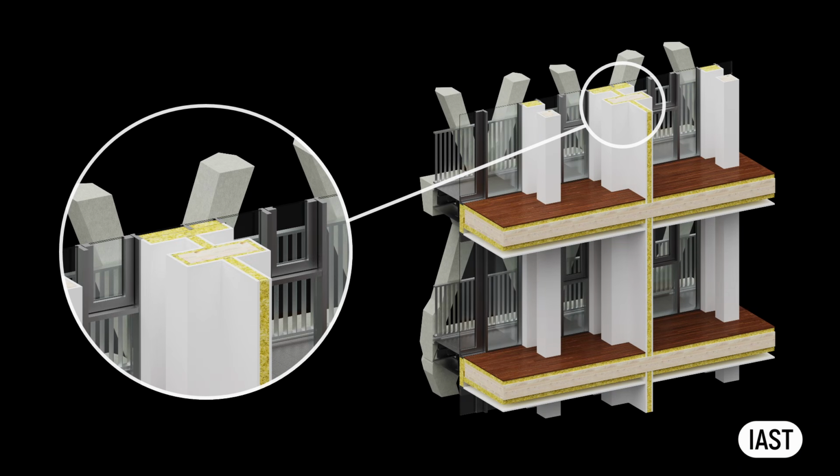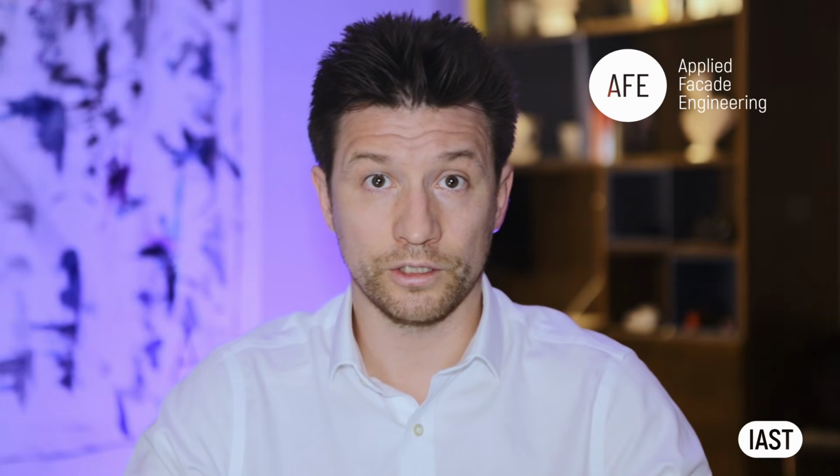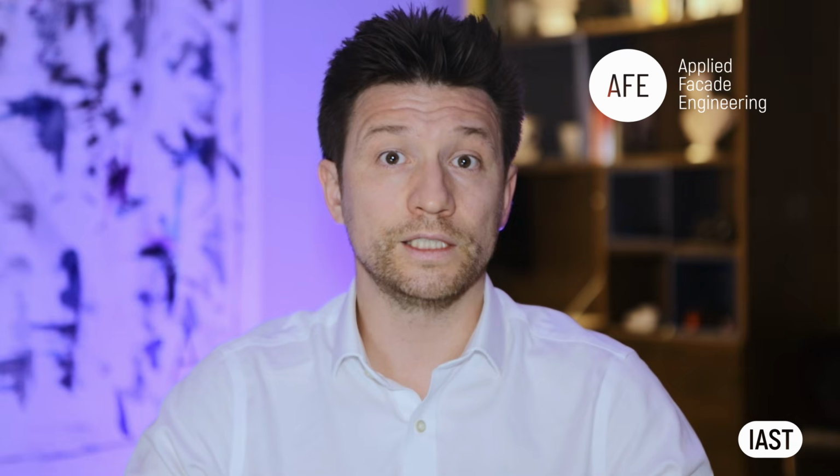When it is used as a primary framework, it should be protected by fire-rated materials. For compliance purposes, its presence in the external walls of tall buildings should be minimized. We will talk about this in the fire safety module. Covering mass timber parts with gypsum boards, mineral wool and concrete also helps with the acoustic performance. Timber shrinkage and how it can be accommodated will be discussed in the movement and tolerances module. Course participants are recommended to take the Applied Facade Engineering course, where we delve into greater detail on these and other materials commonly used in facades.